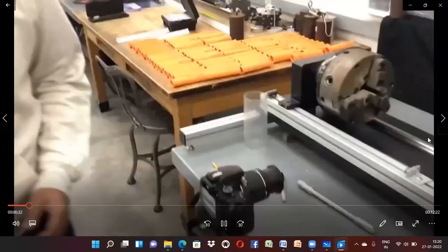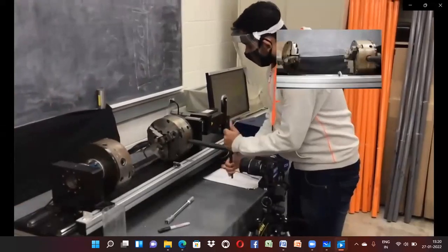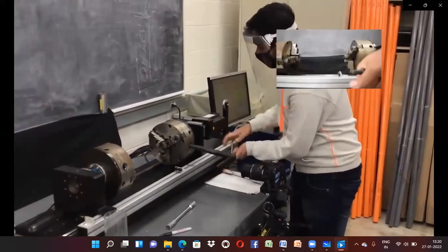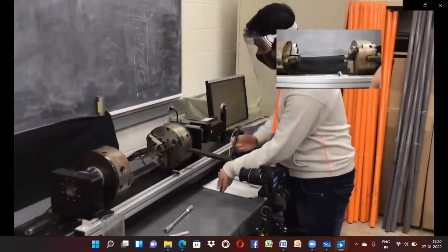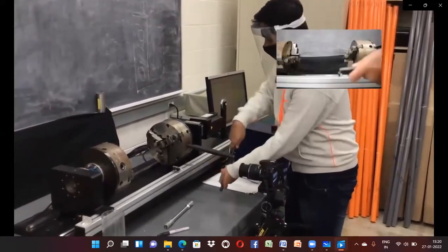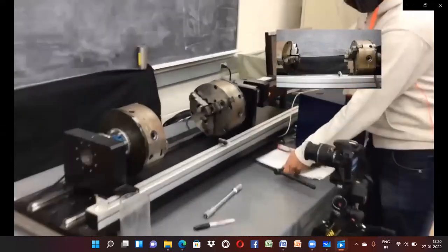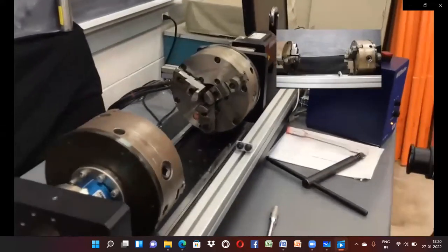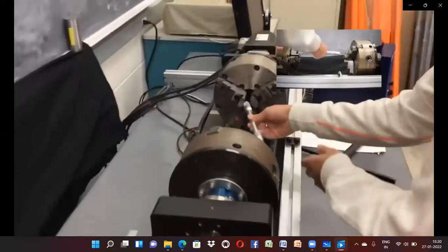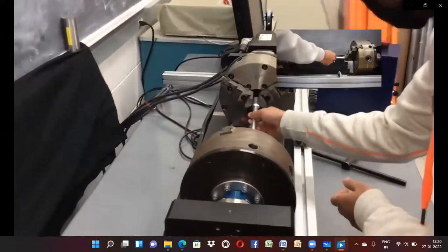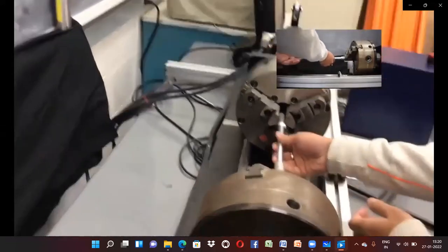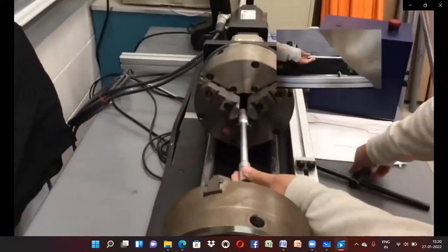Now it's time to actually load a specimen into the actual chuck. For those who have your green pass, you're familiar with the spring-loaded chuck key, right? The reason they're spring-loaded is that you can't accidentally leave the handle in the chuck and then it starts spinning at a couple thousand RPMs, potentially killing people. This, as you'll see, does not spin at a couple thousand RPMs, closer to less than 1 RPM. But nonetheless, we have the spring-loaded chuck just to be safe.